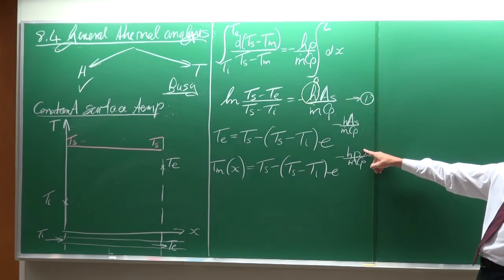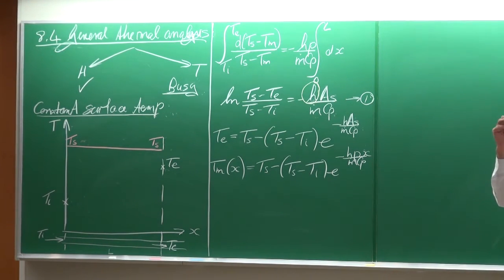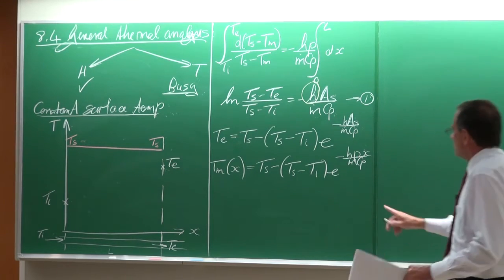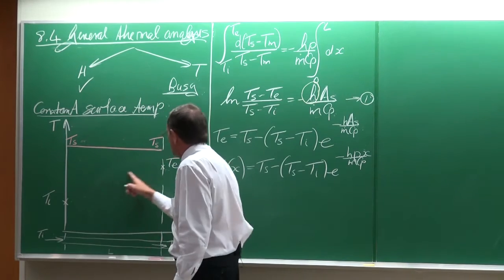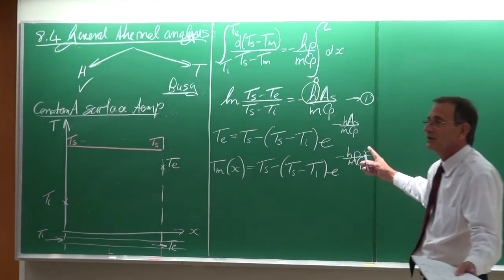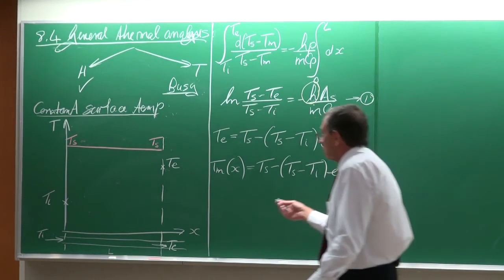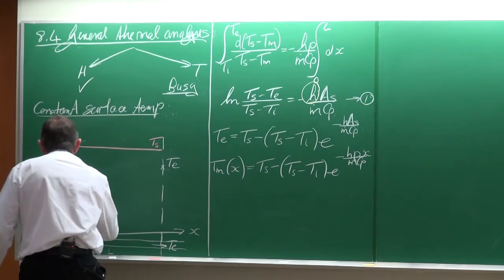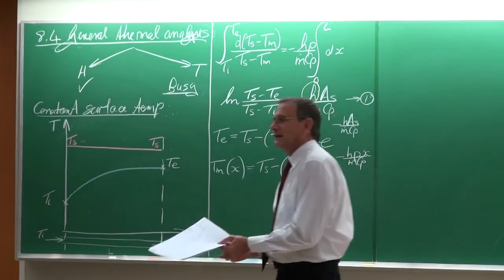And of course, if it is a circular tube, then the perimeter P is equal to pi multiplied by the diameter. So this gives us this equation of the fluid temperature here on the inside. And you can see it's not a linear line. Okay, you can see there we've got the e complication. So typically if you would now go and plot it, you would get a temperature distribution looking something like that.